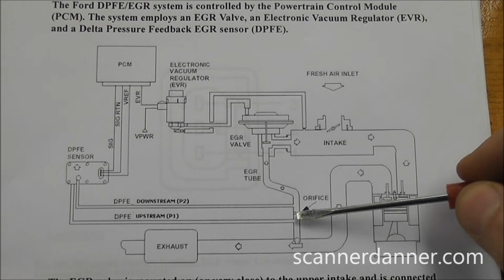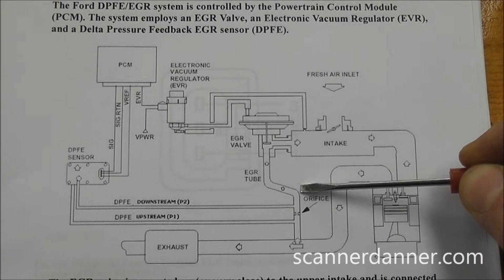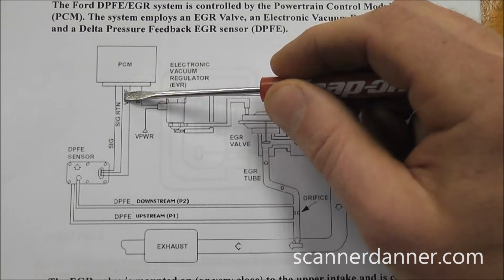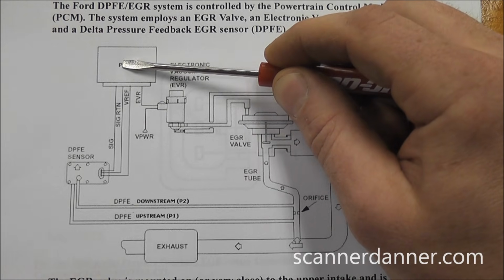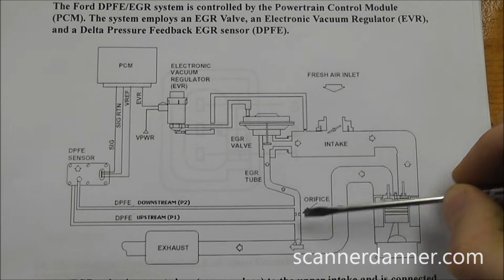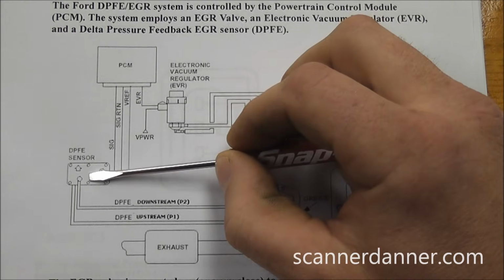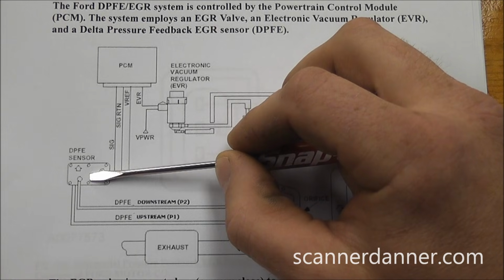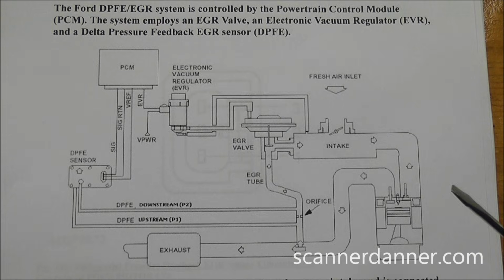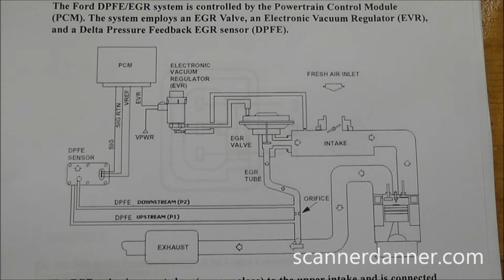And what we'll do is we'll take a sample below the orifice and a sample above the orifice of pressure in this tube. This sensor is going to take that pressure signal, convert it to a signal the computer reads as the amount of EGR flow. When the valve is closed, our pressure in the tube is equal on both sides. And so with no difference in pressure, we'll have low voltage from this sensor. And the range that I saw on the flow chart I used, I think it was 0.35 to 1.3 volts at idle, depends on the car, depends on the design. We'll see a pretty big range.